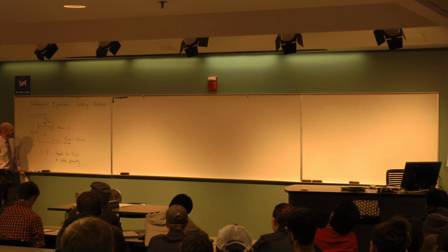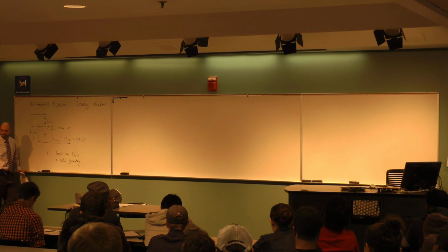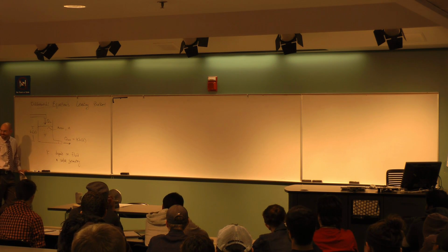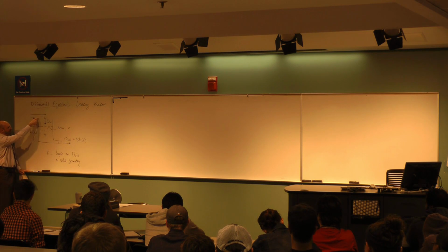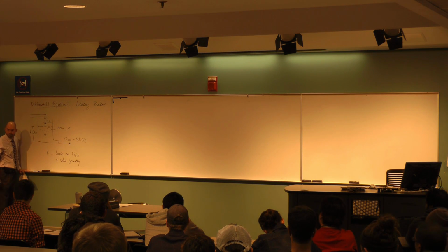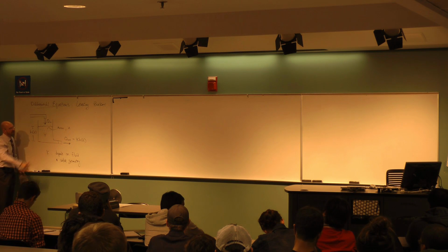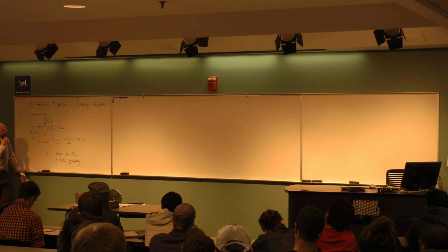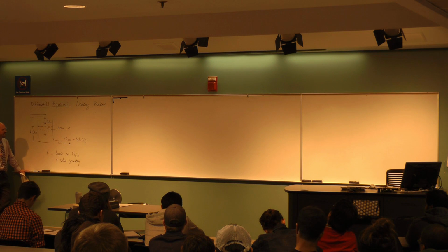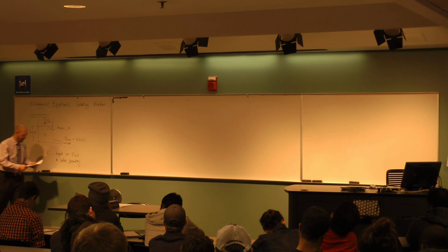And as long as that steady state height is less than the height of the bathtub, then I'm in good shape, right? But if that height is over the top here, then I've got a problem. Okay, so clearly you could come up with this model and answer that kind of question for any container, bathtub, whatever. All right, so we're going to need some kind of equation to solve for the h of t.